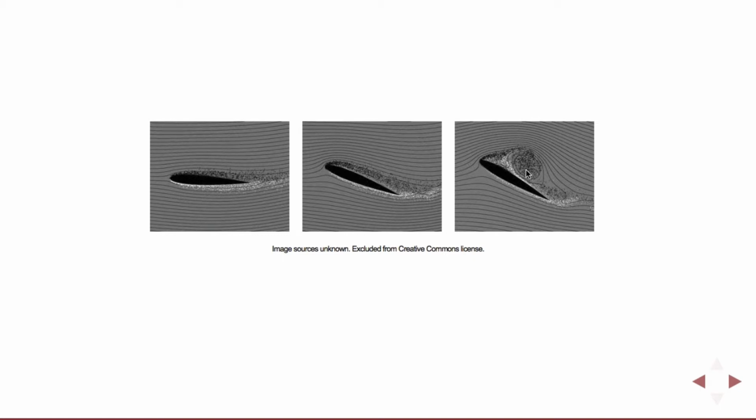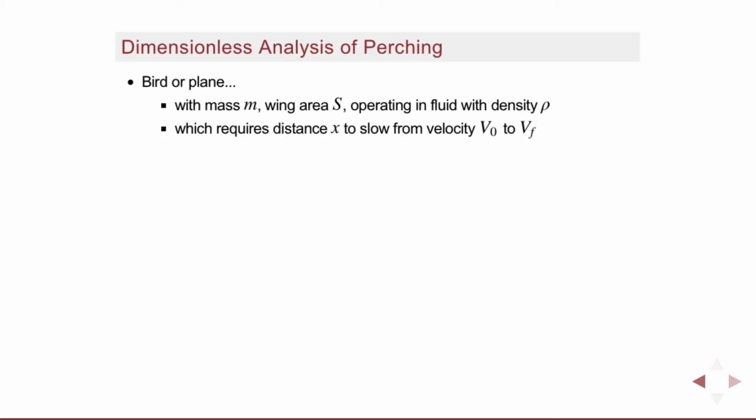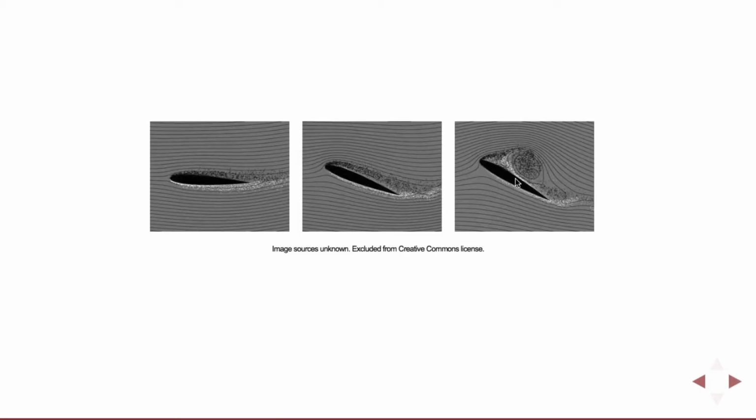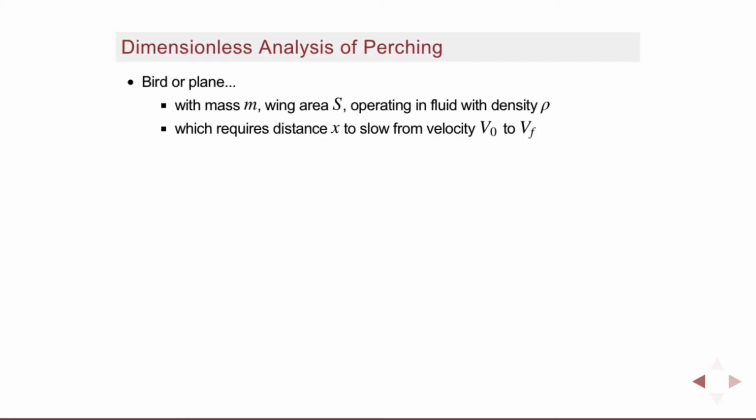And this has generally been considered much, much harder to model, to come up with simple models to describe, and much harder to do control. So most aircraft control systems today avoid this regime completely. Even our best fighter jets have angle of attack limiters, where the autopilot will prevent the pilot from going into post-stall flight because it's a dramatic change and hard to control. So it's kind of fun to think: birds do go into post-stall all the time, and airplanes don't. Do birds achieve a dynamic advantage for doing it?